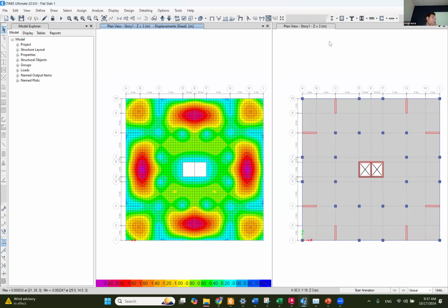Let me tell you something. What happens when we increase the mesh size? Like, the mesh size was 1 meter and was irregular. The software picked the optimum shapes that are going to make the analysis much faster. But when we decrease the mesh size, what happens? We created more points where the software is going to do averaging or interpolation, or do finite element analysis, right? So we increased everything, so we are expecting that it's going to take more time.